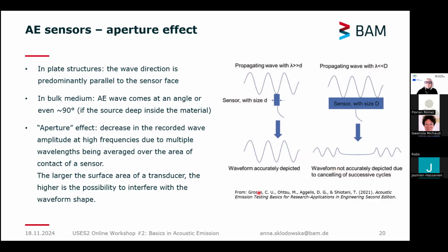And this directly affects the sensor sensitivity curve, since it might differ depending on the excitation location and sensor diameter. Again, the reason is connected to the diameter of the sensor, since the voltage is an integration of the response of the whole contact surface. In other words, the voltage output is derived from the average disturbance over the whole surface of the element.